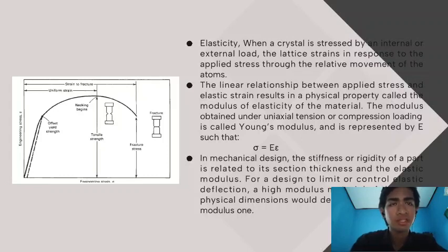The values of the elastic moduli are primarily determined by two fundamental contributing factors: the crystalline structure of the material in question and the atomic bond strengths. The elastic modulus tends to be highest in materials with strong bonding, and the lowest in polymers. Tensile modulus ranges from about 15 GPa for lead to over 400 GPa for tungsten.